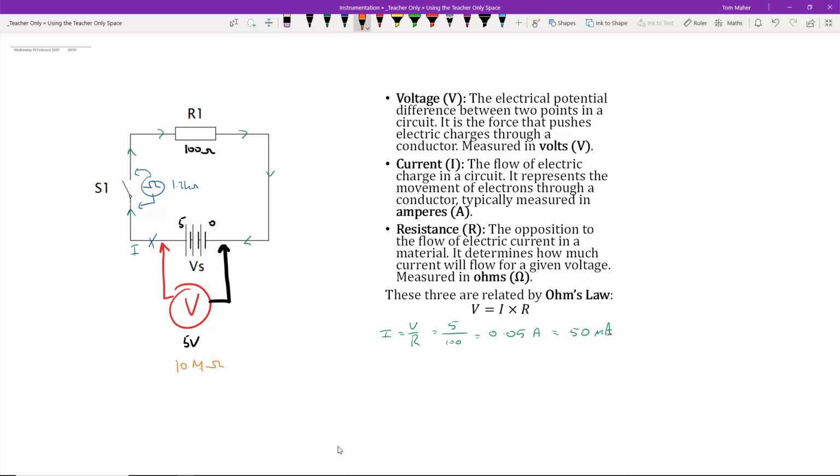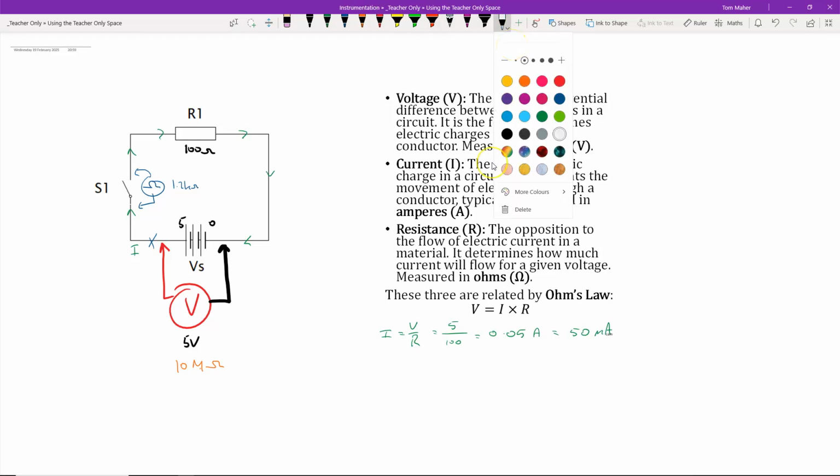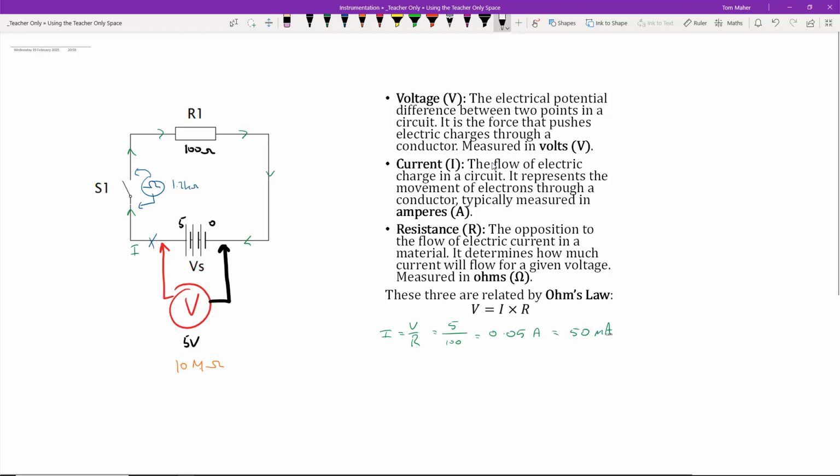When we want to measure current, so I'm going to try and measure the current just through the cable as we have it here. When we want to measure the current up there, we need to put the meter into the circuit. Okay, so what we do is we break the circuit. So let me just break my circuit a little bit here. I need to get up. I will go with this one here. Okay, that'll give me a little break in the circuit there, like that.